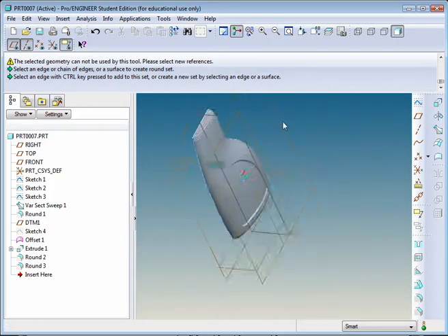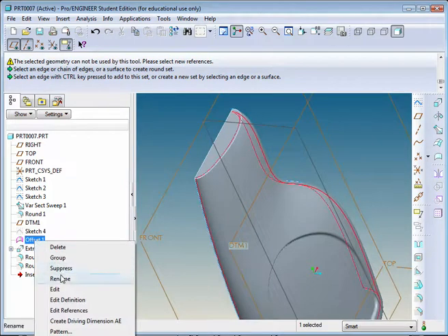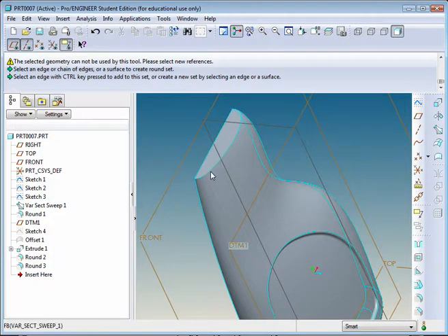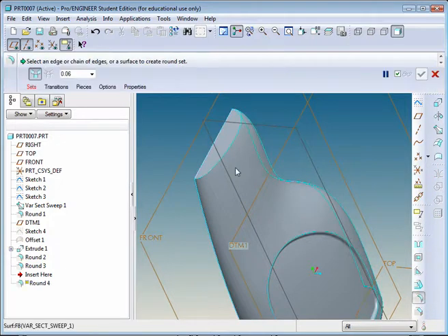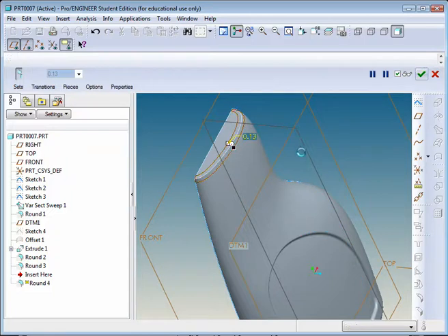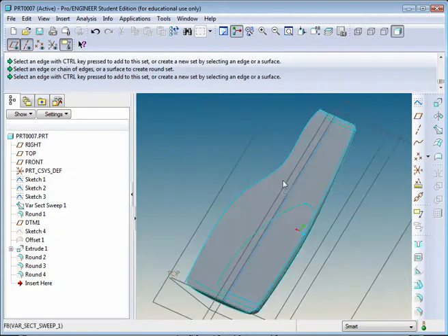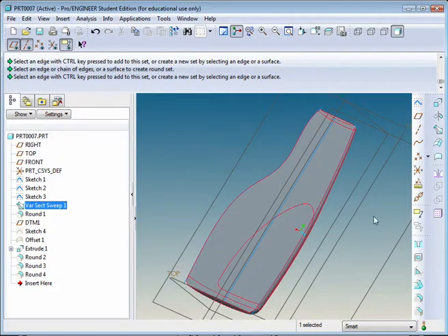Okay, we'll put one more fillet over here. That offset surface, we could right click and hide it if we want, so we don't need to see it. We'll add one more round up at the top here and increase that in size to about 130 thousandths. And from here we could go ahead and mirror this across. So let's select the geometry. Over here on the right you'll find the mirror tool.